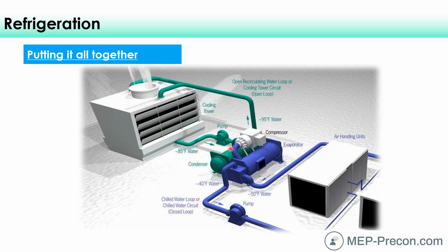And so we're going to absorb the BTUs from that refrigerant, and as such, it's going to heat up that water by 10 degrees or so, from 85 degrees to 95 degrees, and that refrigerant condenses back into a liquid, goes through the expansion valve, comes back into our evaporator nice and cold to be able to absorb more BTUs from the space. But let's follow those BTUs back here.